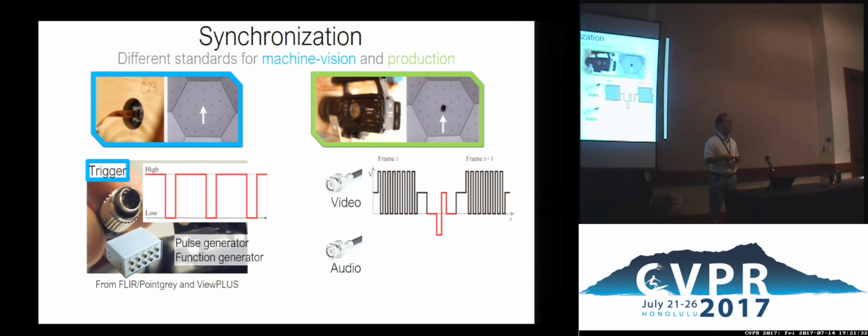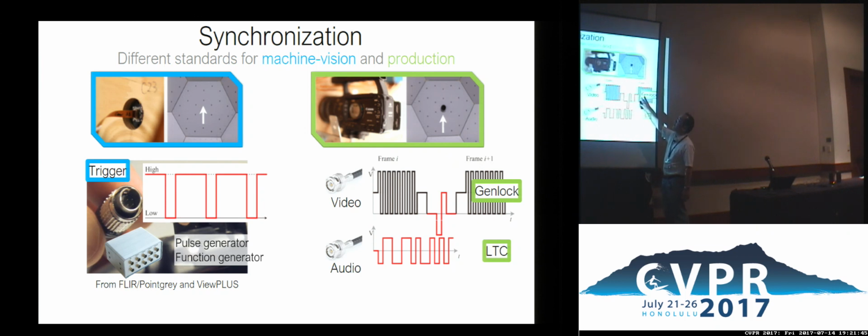As Takeo introduced in his analog video system, we call this a Genlock system, in fact. The reason the camera requires audio is that the audio side provides a timestamp. It's called a linear time code. This is a regular audio signal. You can hear it, in fact. But anyway, it tells that I'm in frame 1, I'm in frame 2, or something, by audio, in fact.